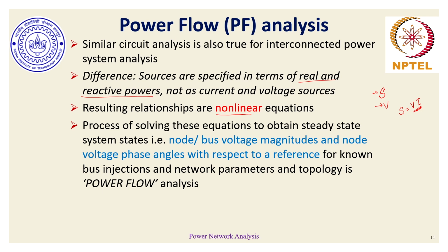And that is where the importance of power flow analysis comes in. Power flow analysis has the same objective, that is, to solve these nonlinear equations to find steady state system states. We call these system states because if we know the voltage phasor of every bus in a given power network, we can find the currents through the branches, the power consumed, the power absorbed, etc.